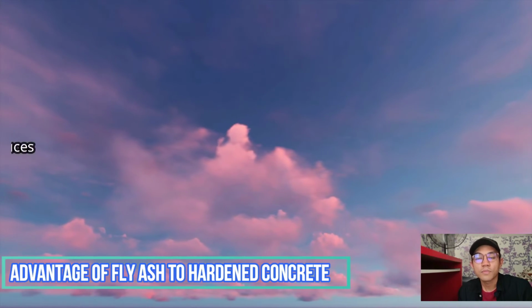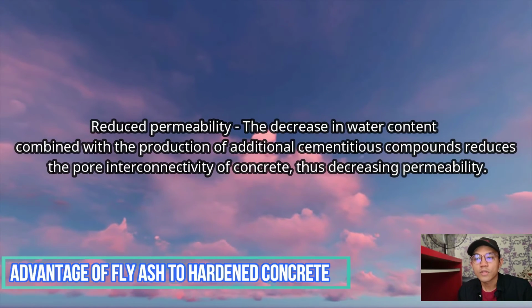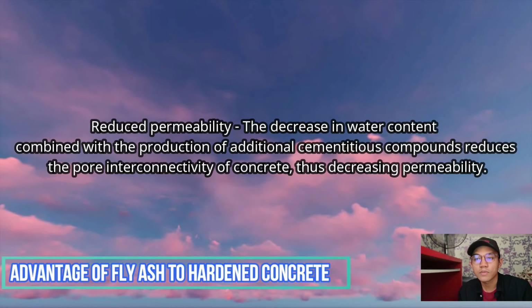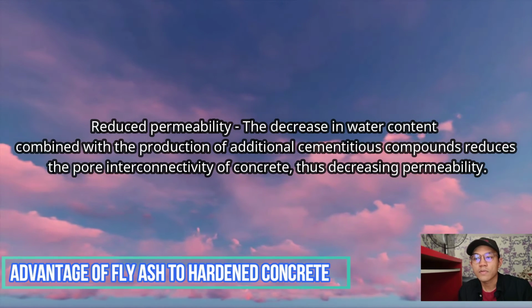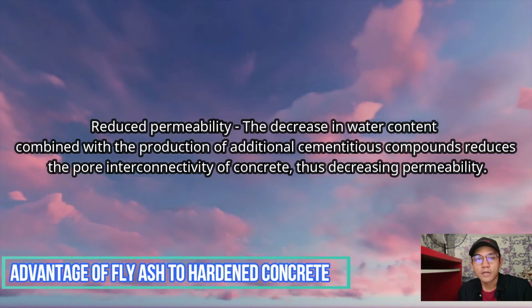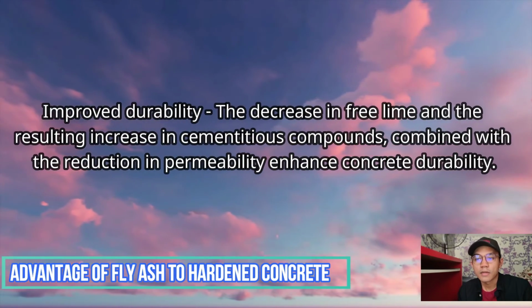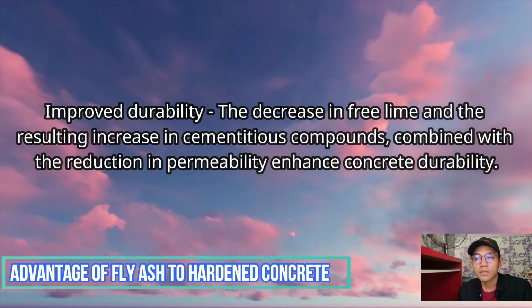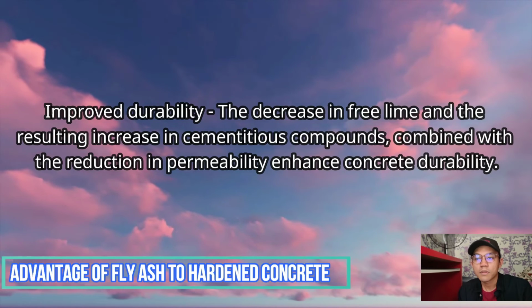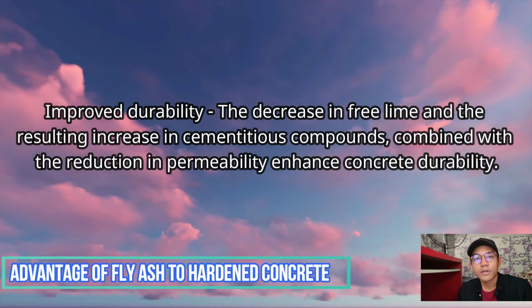Second, reduced permeability. The decrease in water content combined with the production of additional cementitious compounds reduces the pore interconnectivity of concrete, thus decreasing permeability. Third, improved durability. The decrease in free lime and the resulting increase in cementitious compounds, combined with the reduction in permeability, enhance concrete durability.